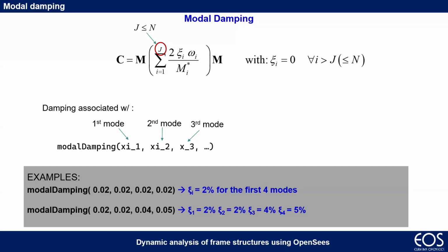So Faisal, this is a convergence problem. Try to plot the convergence curve, the capacity curve, the results of the pushover curve, and the pushover analysis. And then if you still have a problem after iteration 1000, we can discuss that after the lecture, okay?